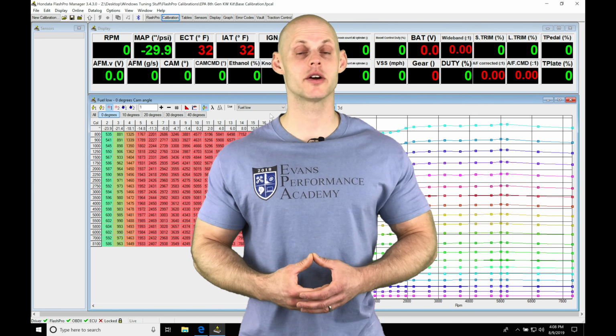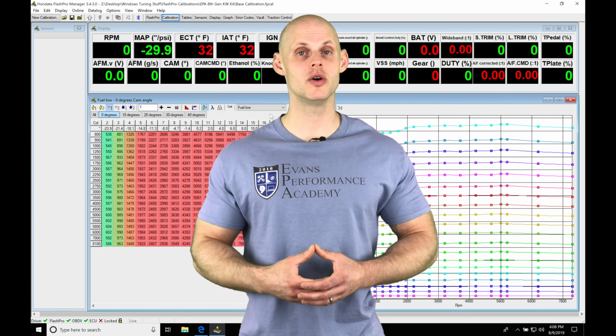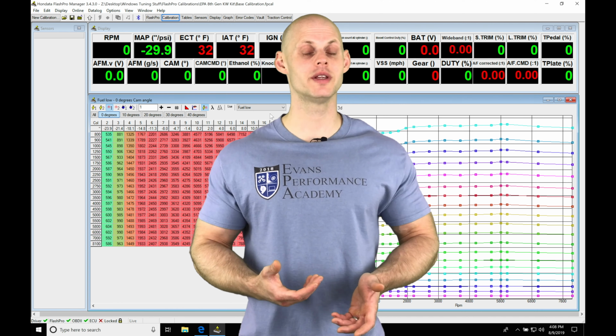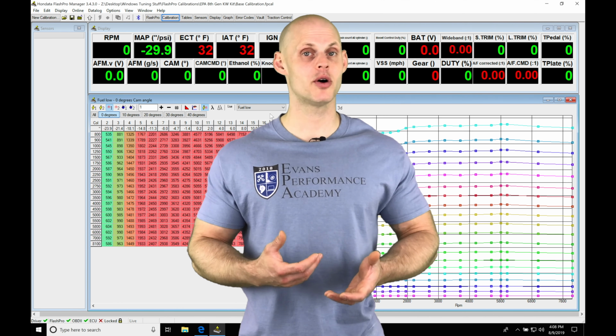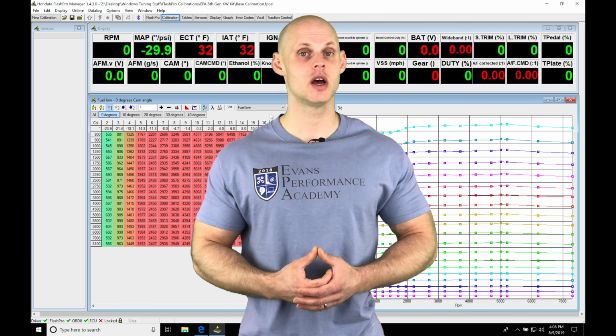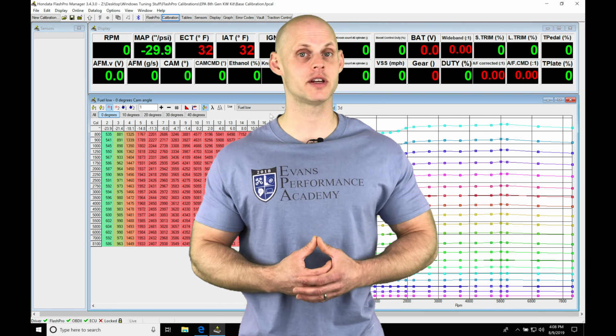In this video, we're going to get our engine fired up and tune our low cam 0 degree fuel and ignition timing tables for idle, part throttle, and wide open throttle conditions. We're going to have a lot to learn, so let's jump into the live training session so we can get started.